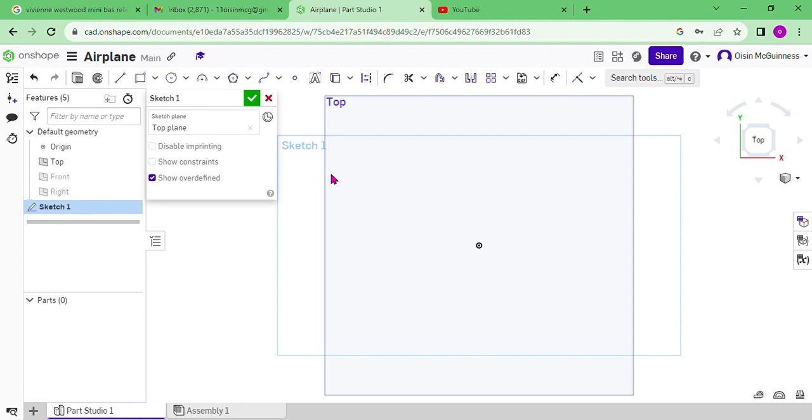So we're going to have to figure out which of these commands we're going to use to start drawing our airplane. So really what we're going to use is our line. Always we're going to start drawing from this origin point, and the first line I'm going to draw is this horizontal line across. Just for the sake of dimension and stuff, I'm going to press escape, so I have my cursor highlighted, escape on my keyboard, and I'm going to press this dimension.